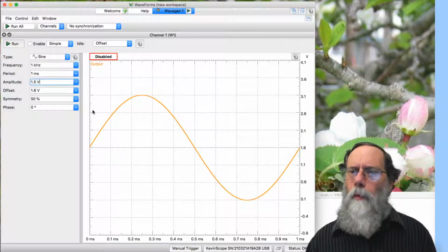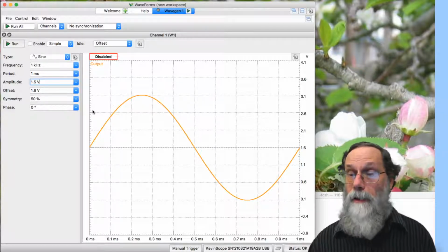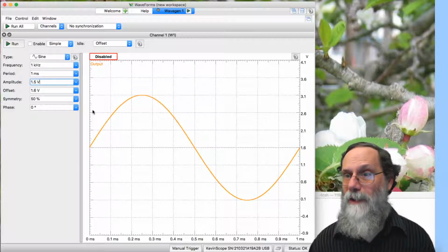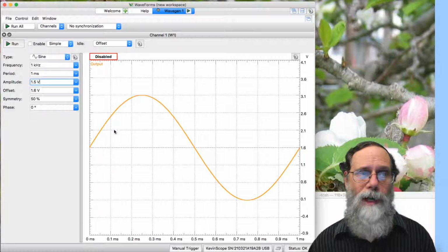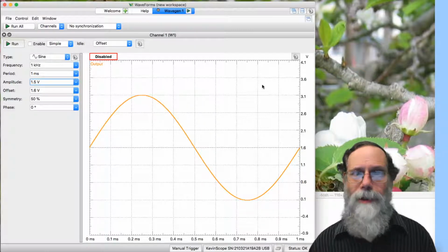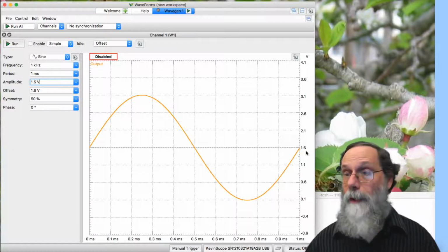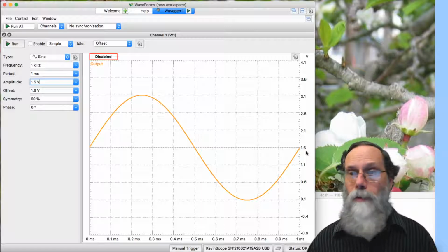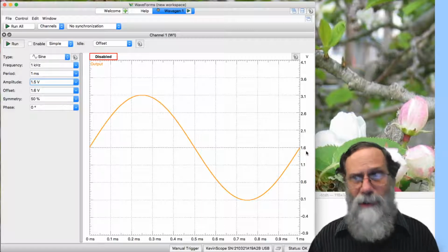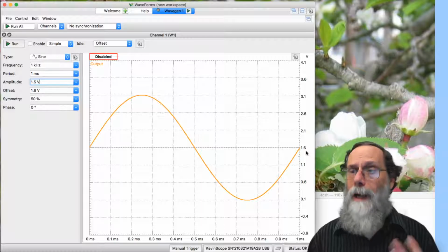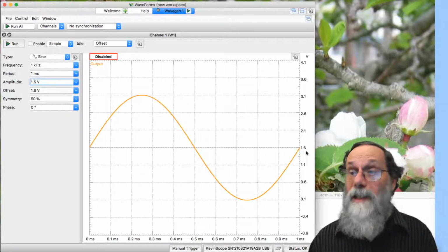Okay, there's a problem with doing sine waves as examples, and that is a lot of times when we're talking about aliasing, we want to talk about negative frequencies, which is a left-right reversal of the signal here. And if I just did a left-right reversal of a sine wave, then I'd be going down and up. And I couldn't tell that any different from a vertical flipping of the thing. Negating the voltage would look the same as negating the time. And yet I want to be able to distinguish positive frequencies from negative frequencies. It's a different phenomenon flipping left and right than flipping top and bottom. So I want to pick an asymmetric signal.